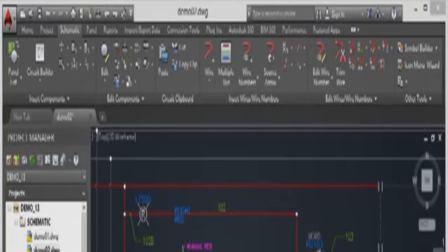Often when you're working in your AutoCAD Electrical drawings, there will be a requirement to delete components from the drawings themselves. Now, I must stress, when you're working in AutoCAD Electrical, you're working with a project database behind the drawings themselves. That's what your project is based on over here in the Project Manager. It's all database driven. So don't just run around the drawing deleting using the AutoCAD erase command or the delete key on the keyboard. Because what happens there is you delete the object from the drawing, but you don't delete it from the database. So always use your delete component command.